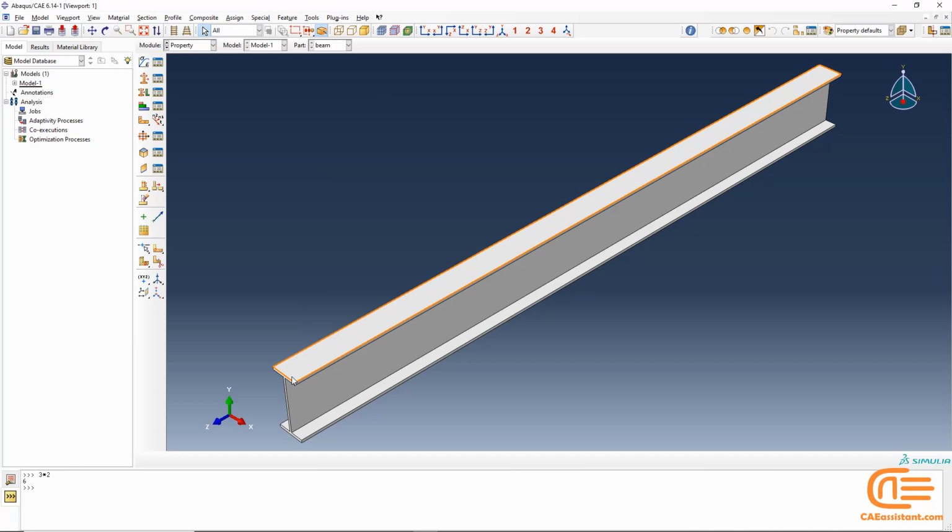Material definition specifies all the property data relevant to the material. You specify a material definition by including a set of material behaviors, and you supply property data with each material behavior you include. You use the material editor to specify all the information that defines each material. Each material that you create is assigned its own name and is independent of any particular section. You can refer to a single material in as many sections as necessary. Abaqus assigns the properties of a material to a region of a part when you assign a section referring to that material to the region.